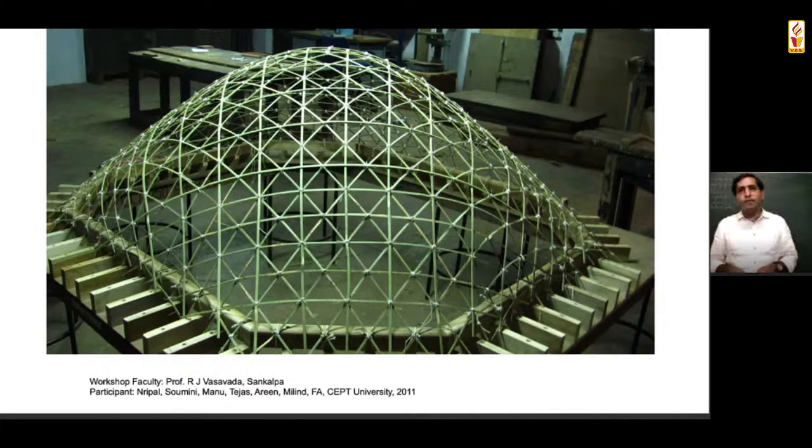So let's say this is a grid shell. The point is that the end condition always becomes a problem. So observe this: if we have not resolved the detailing in the end conditions, we cannot get it. The other thing is, whether you are making a synclastic or anticlastic form, the grid has to rotate, because the uniform grid changes into a parallelogram or some kind of rhombic form. That's the only way you will be able to get this kind of form. But there is a challenge to it. I will talk later about what the problem with it is. Go next.